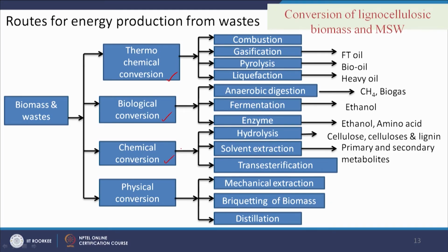Now, we have come to know that some part of the MSW which has high carbon and hydrogen content and heating value can be converted to energy. That conversion can take place basically through thermochemical conversion, biological conversion, chemical conversion and physical conversion. Physical conversion includes mechanical extraction, briquetting of biomass and distillation. These are the prerequisites for some other types of conversions. And thermochemical conversions like combustion, gasification, pyrolysis, liquefaction, which